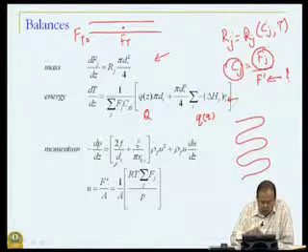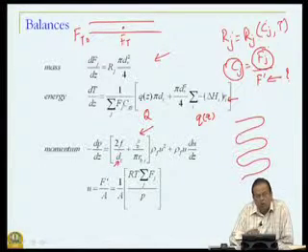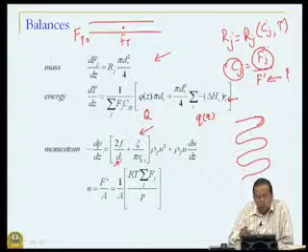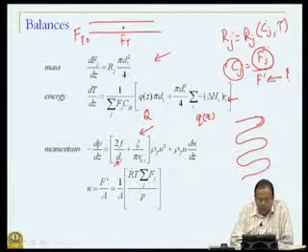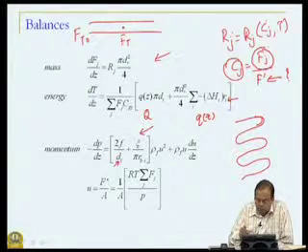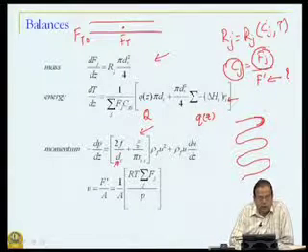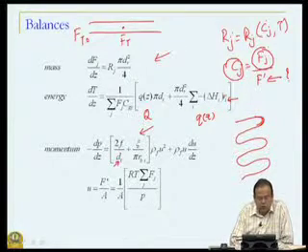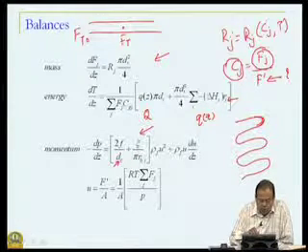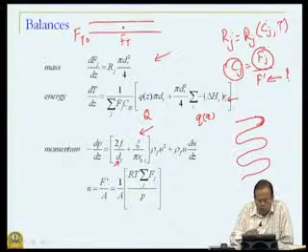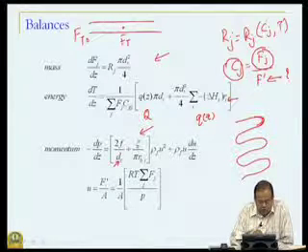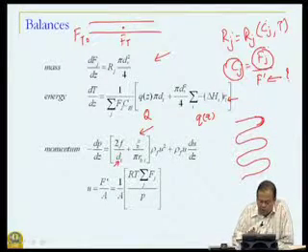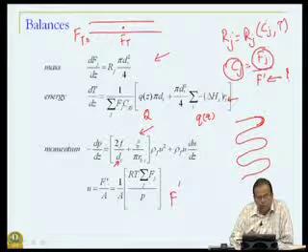This term is familiar, the friction factor term, and this is to account for the bend, the pressure drop across the bend. So, zeta is that shape factor, pi R B, for example the radius of this bend, and so on. So, we have now our momentum transfer, and momentum transfer has the velocity u for example, which is the flow rate F prime by A.